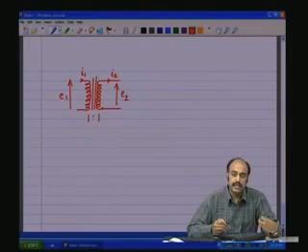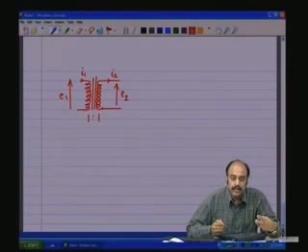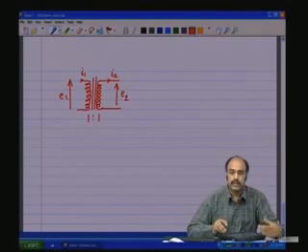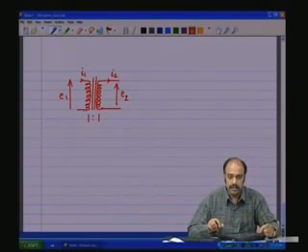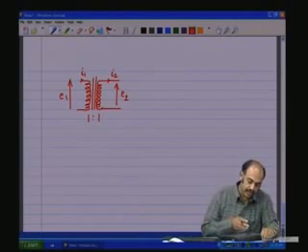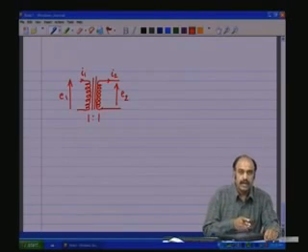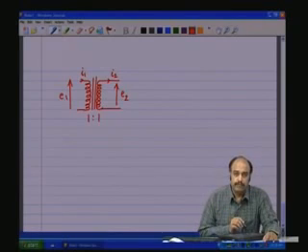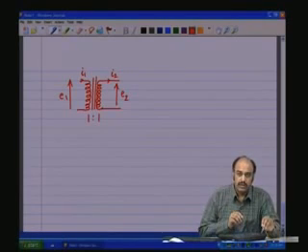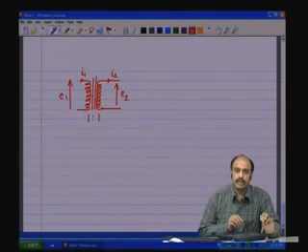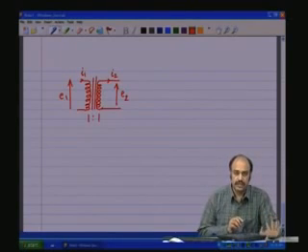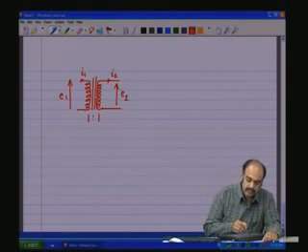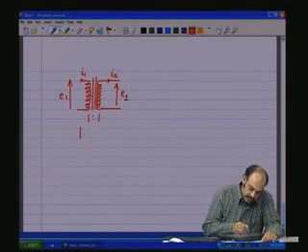The main function here is that galvanically the primary portion of the circuit and the secondary portion of the circuit are isolated, meaning there is absolutely no contact between them. For such applications where one uses a transformer just for the purpose of galvanic isolation between one part of the circuit and another part, such a transformer is called an isolation transformer.